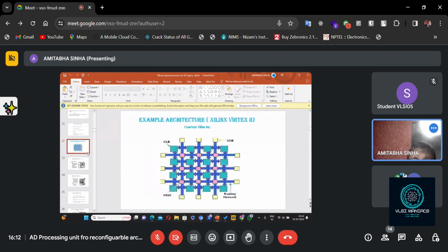So here, the fundamental thing is first some CLB, because whenever we are designing, our concepts should be system concepts and a top-down approach. So our fundamental building blocks will be CLB, IOB, and router. If we can write the code for each of them, only one, then utilizing them and connecting in proper fashion, we can make the design, depending on the complexity.